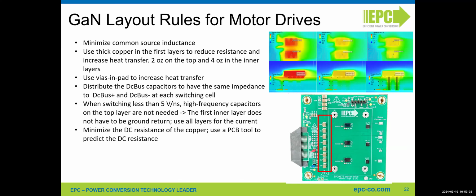If you have a good thermal capacitance, you can have a bigger peak operation. If you have a small thermal capacitance, then you cannot have a big peak operation. And the copper around the device helps you in terms of thermal capacitance. So it's just a trade-off, depending on the application, what you want to do and how much current you want to process.